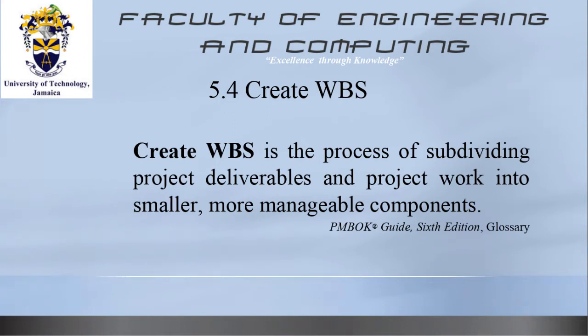And when we have done the design, we go to the various regulatory agencies, to include the local parish council, NEPA, etc., and we make a submission for them to approve the drawings. So let us say we have all our approved drawings. We then go to the university council for approval to construct, because they have to appropriate the funds, right? And they appropriate the funds. Now we have the money, we have the design, we know what we want to do. We now know what it is that it will cost, because we have done the cost estimation and we have the funds appropriated. We have to go through a process of selecting contractors, right?